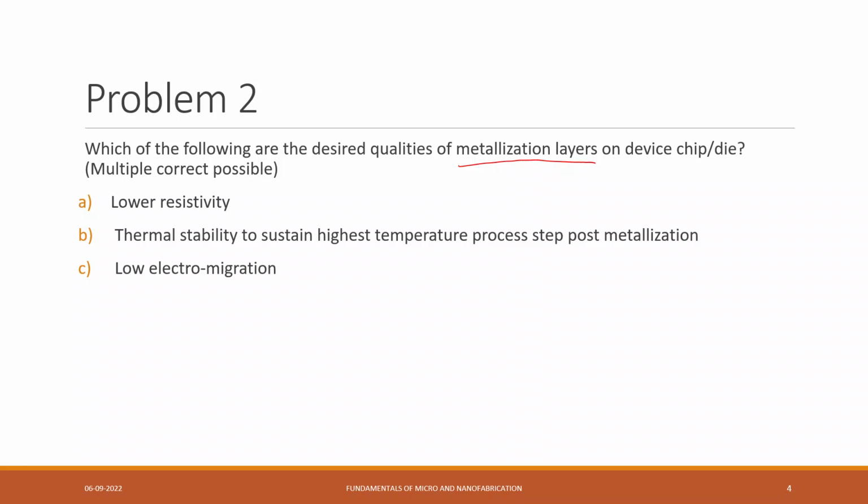So for a metallization layer, we mostly do metallization for having the conductive property of our devices. You can construct devices that are semiconductor in nature or insulator in nature, depending on the coatings we do. For insulating, we do silicon oxide coating. Similarly, metallization layers are done to make an electrical contact on such devices. So the purpose of metallization is the conductive part.